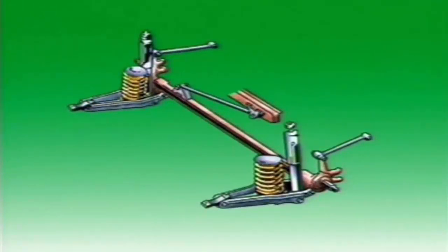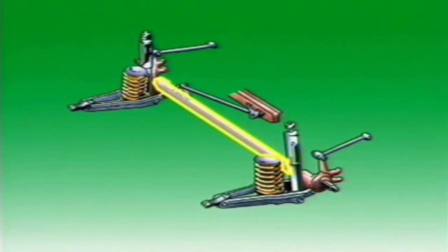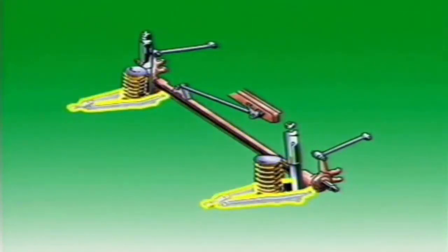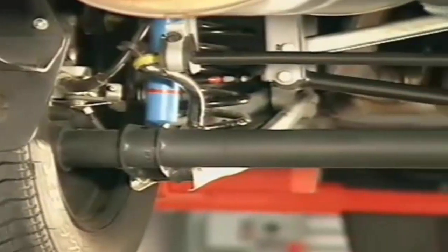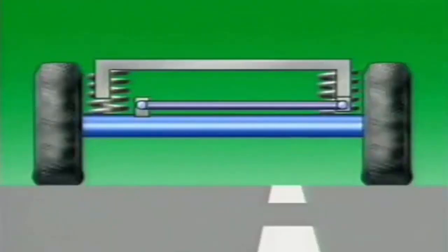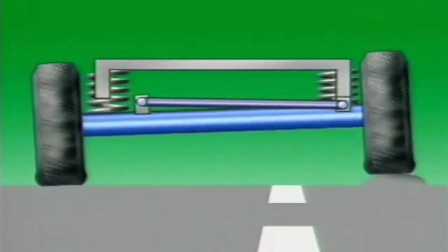On front-wheel drive vehicles, a simple beam axle can be used on the rear with coil spring suspension and control arms for location. This is called a dead axle, since it only supports the vehicle and doesn't transmit any drive. It is also non-independent, as deflection of a wheel on one side of the vehicle will be transferred to the other wheel.